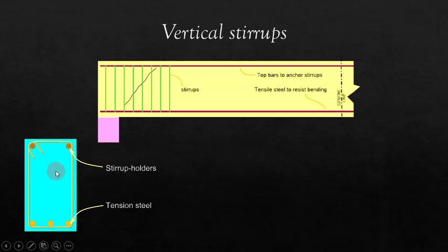Here, the stirrups have two legs. Such stirrups are called two-legged stirrups. In some cases, to resist more significant shear stresses, it becomes necessary to provide several-legged stirrups such as four-legged, six-legged, etc. It is desirable to locate the hooks of the closed stirrups in the compression zone.